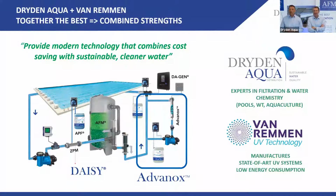So this is not a new technology. This has been used in water treatment for a couple of years. What is new is, again, our genius boy, Dr. Howard Dryden. He is the first who brought this to the pool industry. He said, Dominic, let's combine this. If we have a daisy system, we have mainly organochloramines. And if we pass just a small amount of this water through advanced oxidation, we will break up all the components which are in this water, and we will solve the problem with combined chlorine.